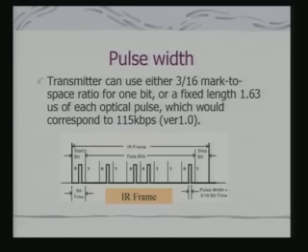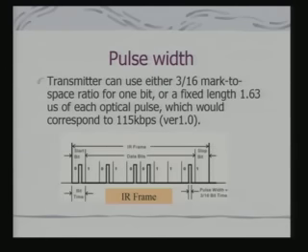So what is really asynchronous transmission? If we look at a UART, we have seen that almost all the devices, all the microcontrollers, they have a UART interface. Typically UART supports asynchronous transmission, and in an asynchronous transmission what happens? Typically clock is not part of the data. You have a start bit which indicates beginning of the data, and a stop bit which indicates end of the data.